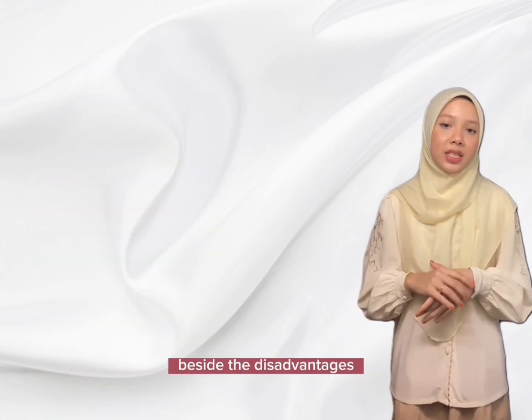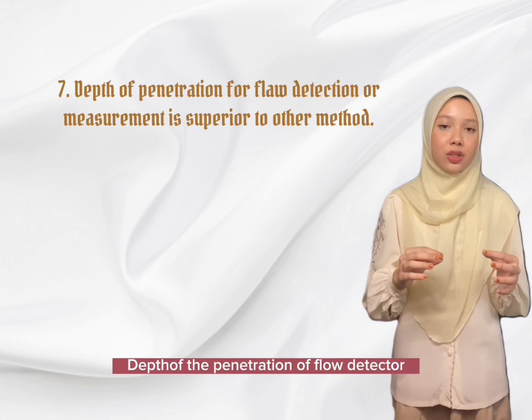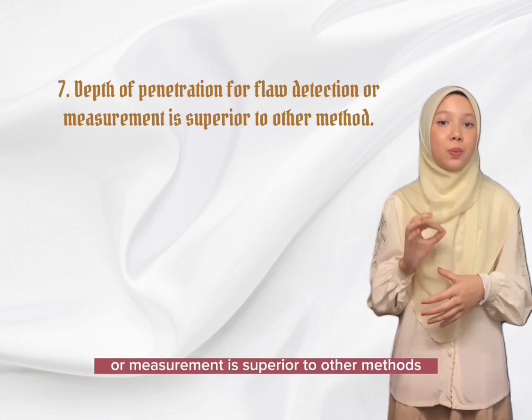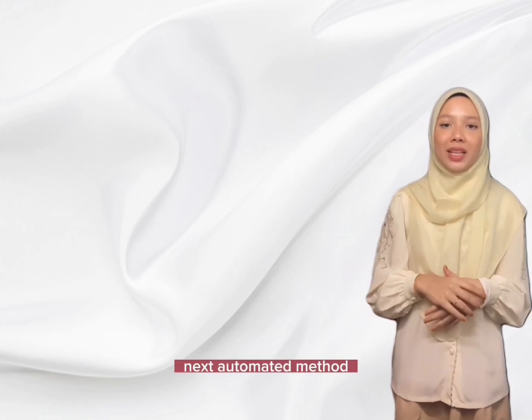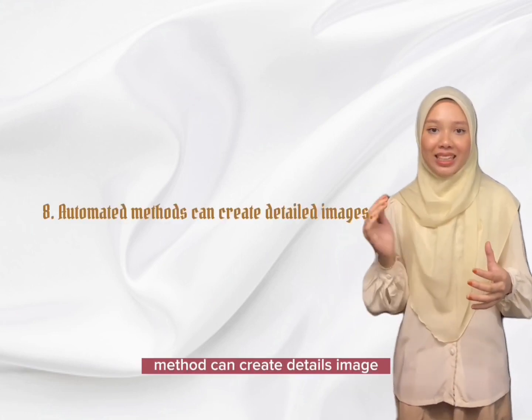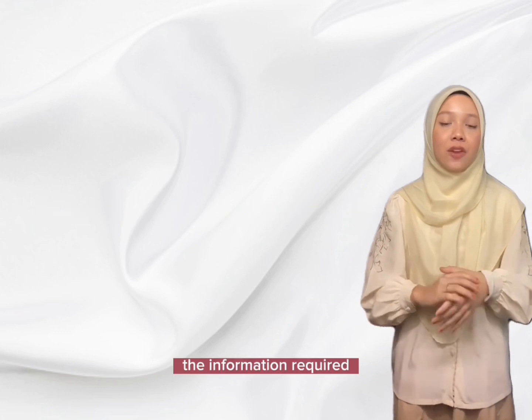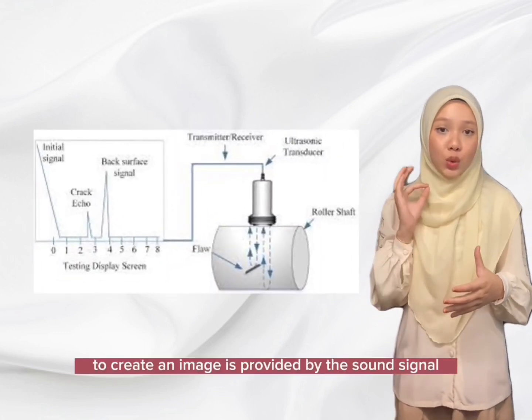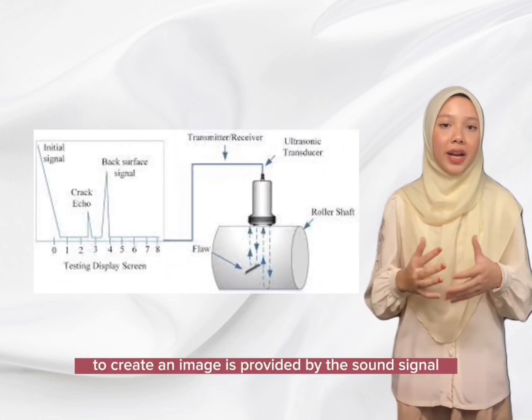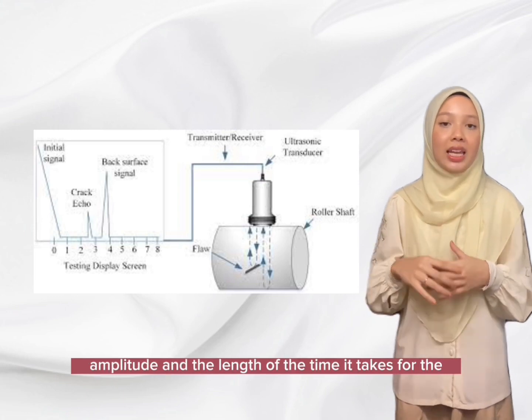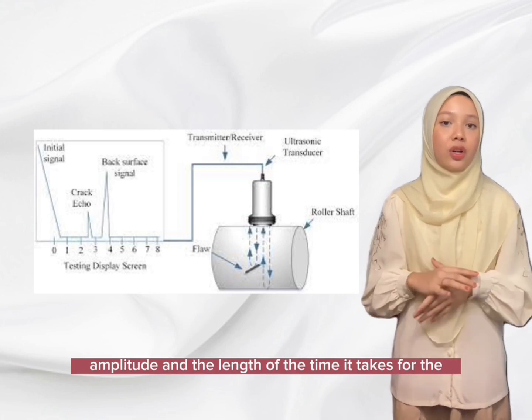Besides, the penetration of flaw detection or measurement is superior to other methods. Next, automated methods can create detailed images. The information required to create an image is provided by the sound signal amplitude and the length of time it takes for the wave to cross the body.